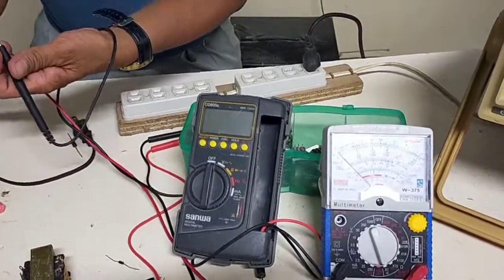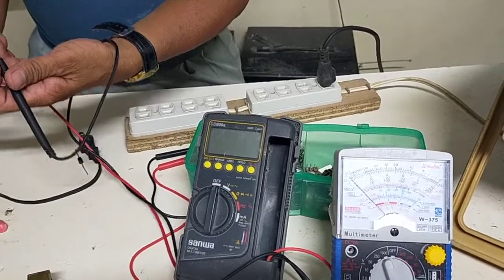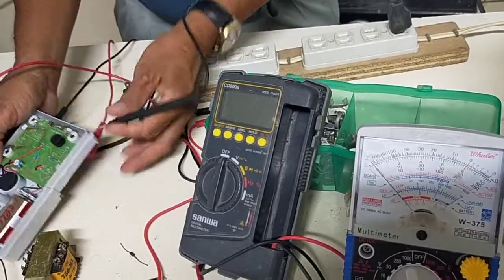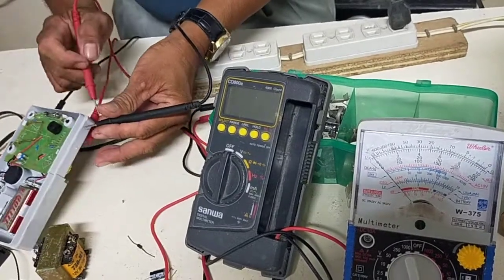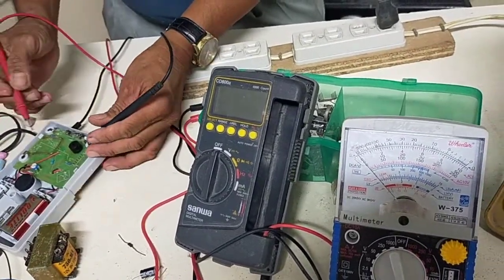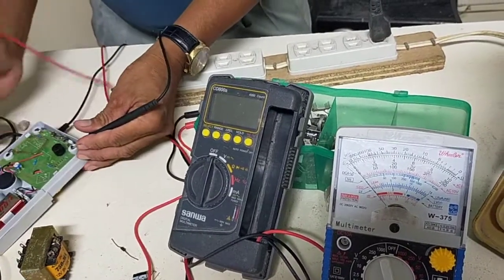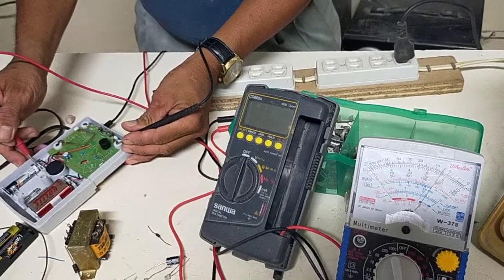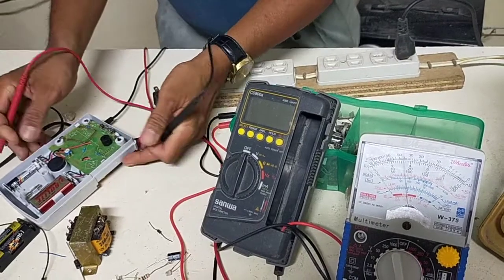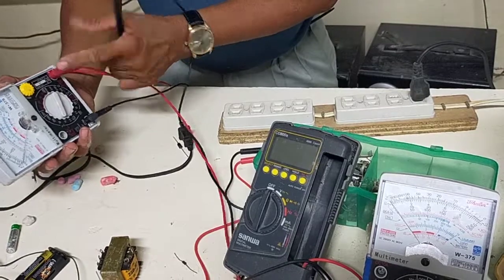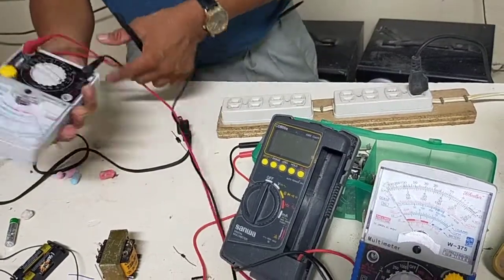Then, see that this is the positive side because it is red for the voltmeter and ammeter. But for the ohmmeter, this is negative because this positive jack that connects the red test rod is connected to the negative side of the battery. This would mean that this is negative for the ohmmeter and this is positive. That is why